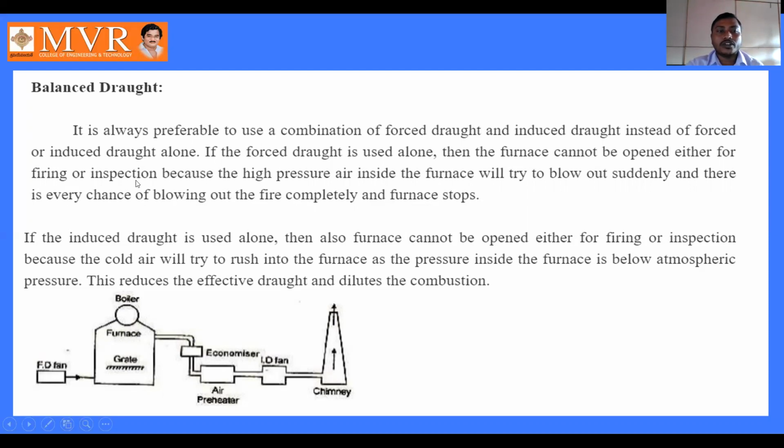Instead of a forced or induced draft fan alone: if the forced draft is used alone, then the furnace cannot be opened either for firing or inspection, because the high pressure air inside the furnace will try to blow out suddenly, and there is a very high chance of the fire blowing out completely and the furnace stopping. For this reason we use both fans for balancing the draft.